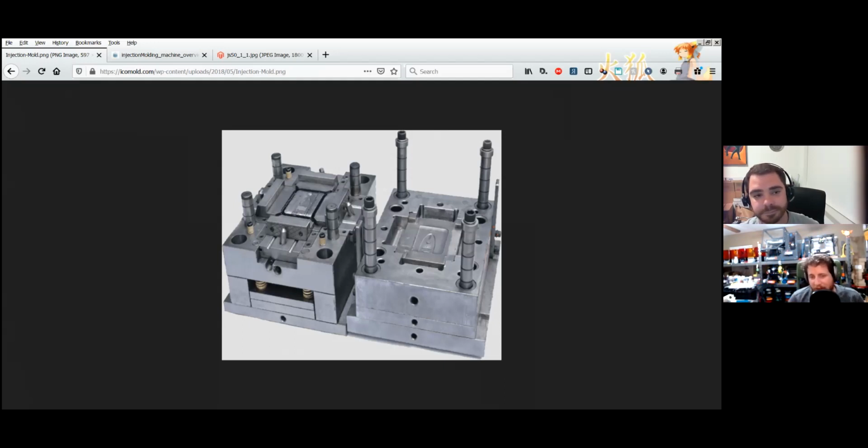See, the big issue with injection molding is you have to make that big slug of steel. And that's going to take a long time because you have to understand everything that goes into making a freaking face shield. All the draft angles, where the ejector pins have to be. Can you do it with just one sprue, or do you need more? How many pieces can you fit on a mold? Those are all time-consuming things. And it normally takes about a month from start to finish to produce an injection mold. And 20 to 50 grand, depending. Oh, yeah. Let's not even talk about the price.